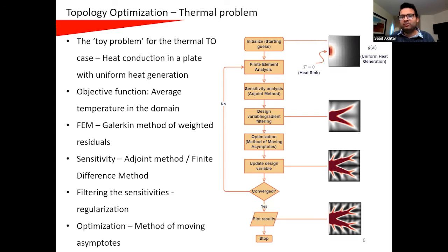So if you want a finer accuracy in your finite element problem, you have to discretize it fairly well. And so each discretized element is a variable of your topology optimization problem. And for complicated problems, you can imagine that could result in hundreds of thousands and even millions in some cases of design variables. You got to figure out a way of formulating your optimization problem and choosing an optimization framework that can accurately solve that.